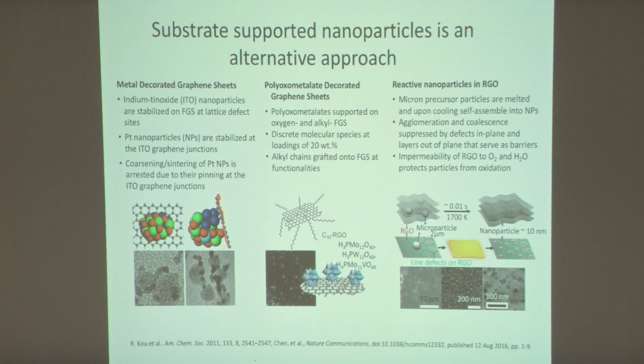Okay, so then the nanoparticles become bonded on the graphene, and as the graphene sheet heats up, the conductivity of the graphene sheet is very high, but as the particles heat up, they remain pinned at the locations, and again, you prevent the nanoparticles from sintering, and so you preserve the initial surface area.